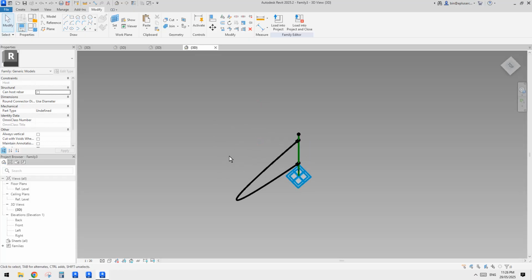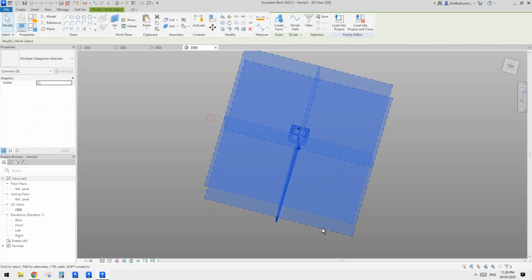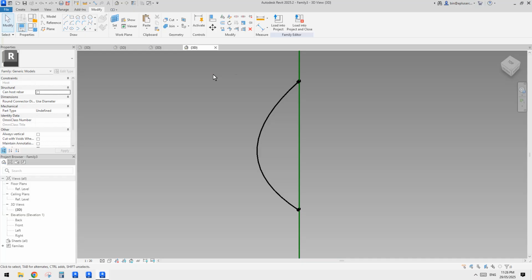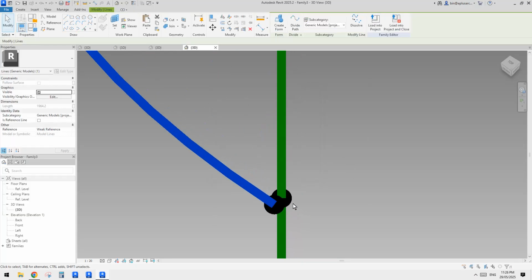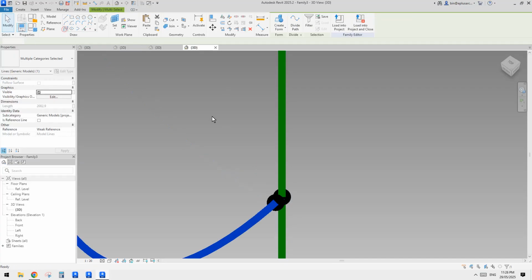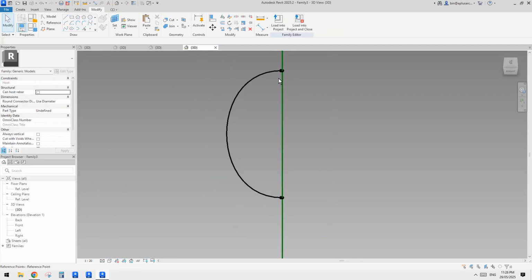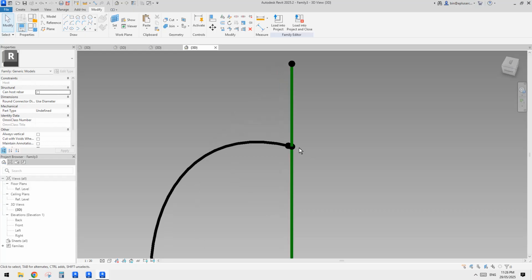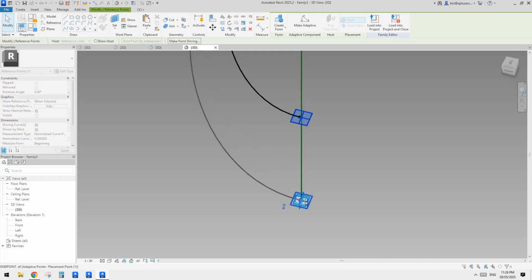Why? Actually, I don't know why. Okay, that's fine. Let's just select it this way, and also control select the point here. Then click on spline through points again. So this will adjust this to use all these 4 points. Now we can select this point, drag this up, and this one can be dragged down.